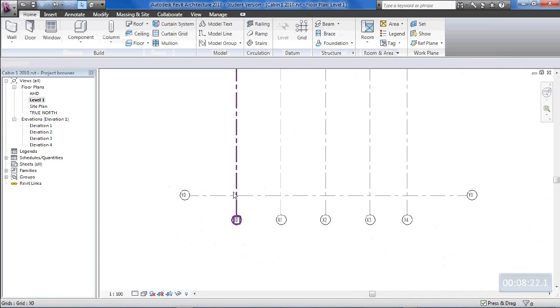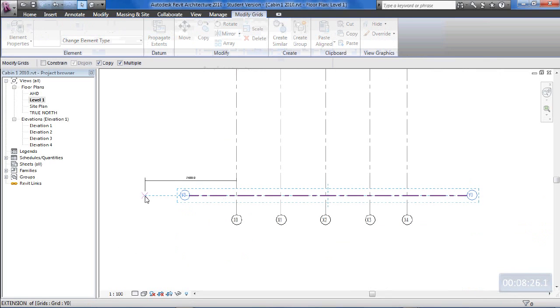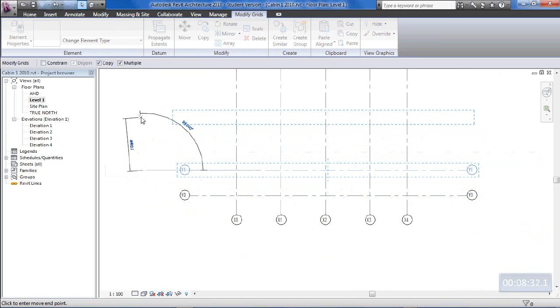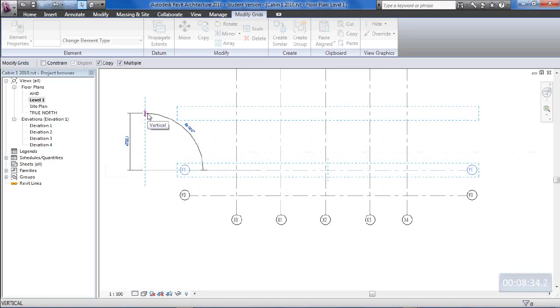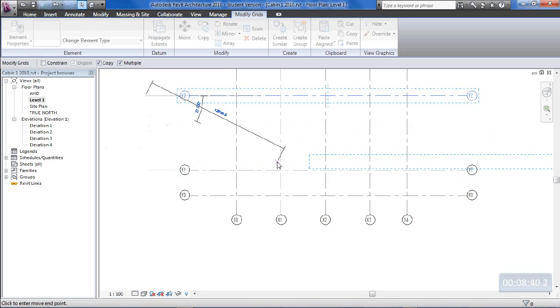Now that was 2100 for the veranda, and then I'll copy it again, was 6150, and press enter, and we might even leave that as the major grid setouts there for that point. So get to an arrangement something like that.